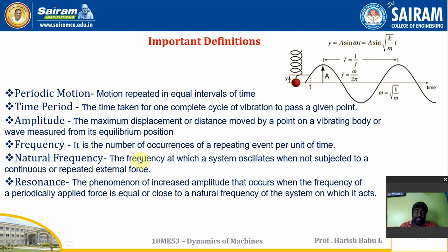Knowing the natural frequency is very important for design engineers, because it gives a complete analysis of the structure. When you go for resonance, resonance is a major phenomenon that has to be taken care of by engineers, to avoid it. Resonance takes place when the working frequency of an object becomes equal or near to the natural frequency. Then there will be fluctuation and the amplitude will increase. That phenomenon has to be controlled to have a proper vibrating system. In the next video, we're going to see the major parts of the vibrating system.